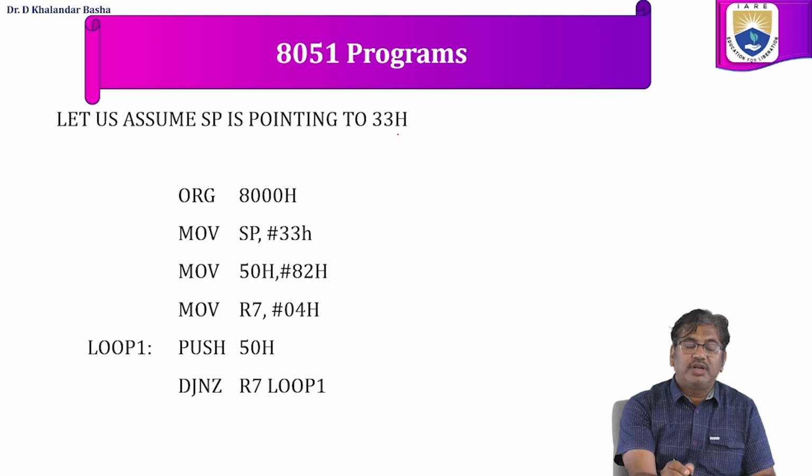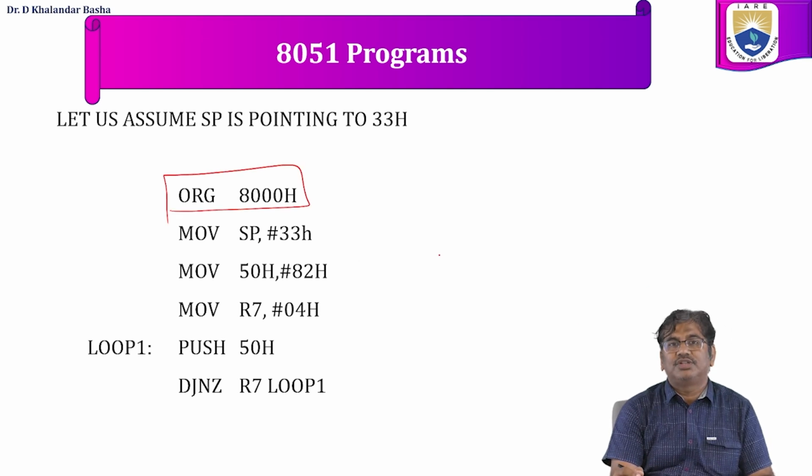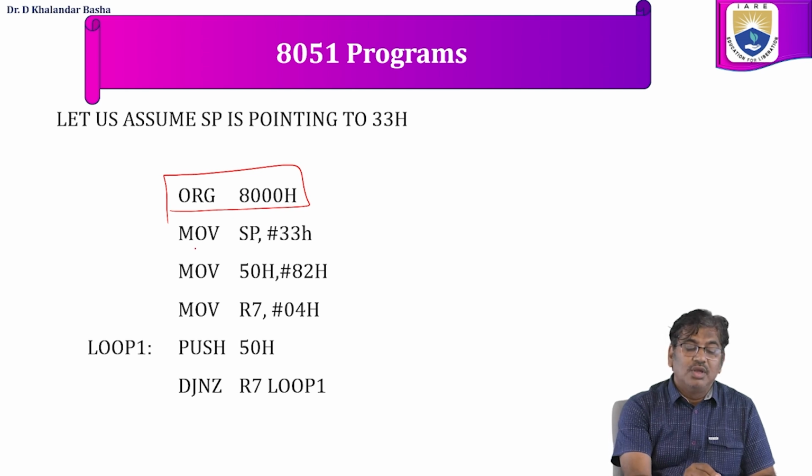So here the stack pointer has the starting address 33H. The entire program is shown at a glance. ORG 8000H is a directive to indicate where the program has to reside. So at 8000H, the program is loaded. Move stack pointer with 33H.